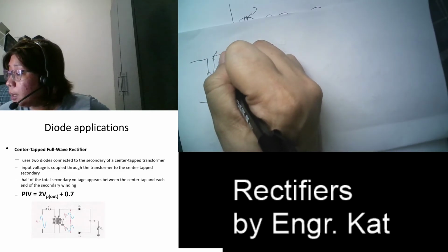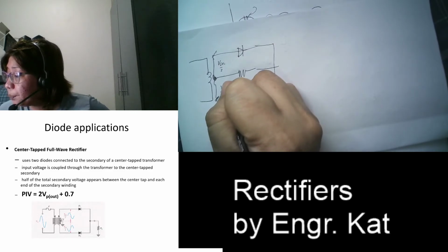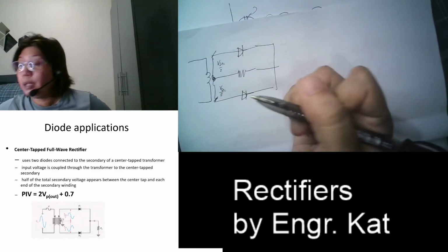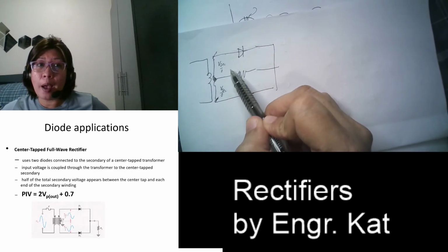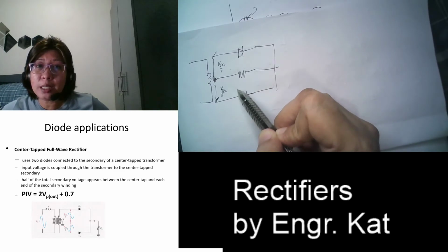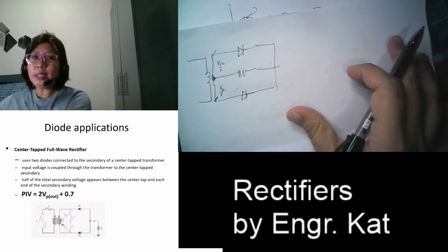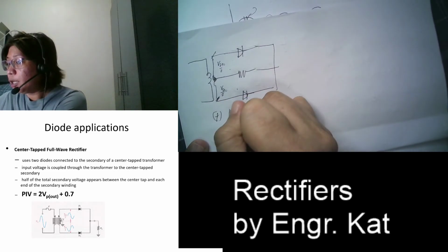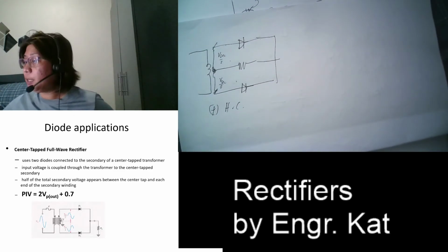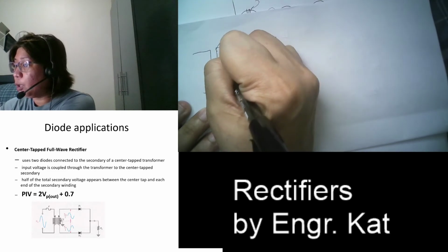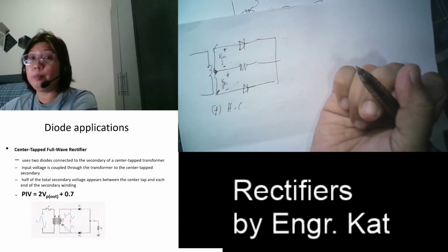So this means this is secondary voltage divided by 2. Okay, so this first circuit here will have half of that secondary voltage, and then this circuit here will have half of that secondary voltage. Okay, so let us say during positive half cycle. So what do we mean by during positive half cycle? So during positive half cycle, this will give me plus or minus my input, and this will also give me plus and minus my input.